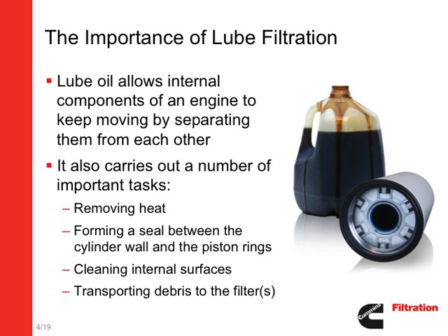Modern diesel engines designed to meet stringent emissions regulations and achieve long service life utilize precise fits and clearances to accomplish these goals. Lubricating oil allows internal components of an engine to keep moving by separating them from each other. In addition, engine oil removes heat, forms a seal between the cylinder wall and piston rings, cleans the internal surfaces, and transports debris to the filter or filters, allowing it to be removed from the system.